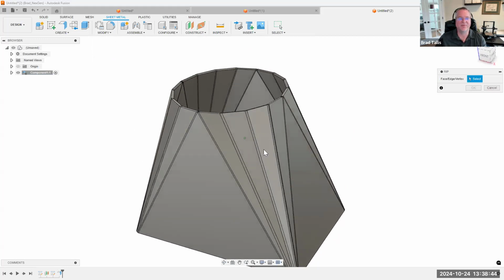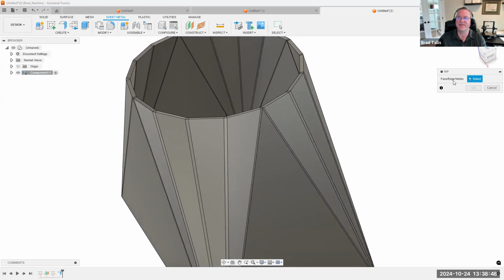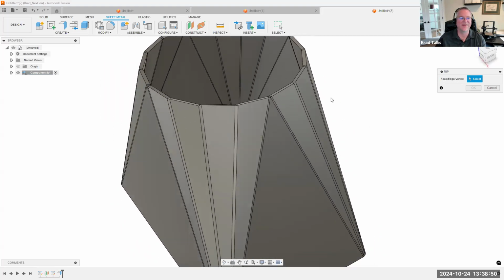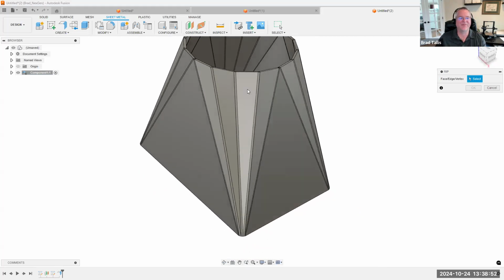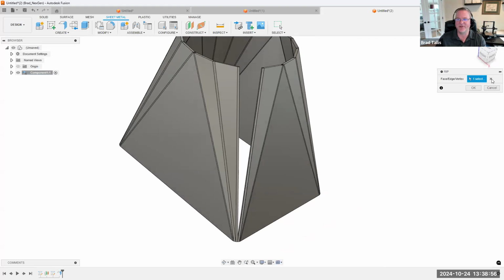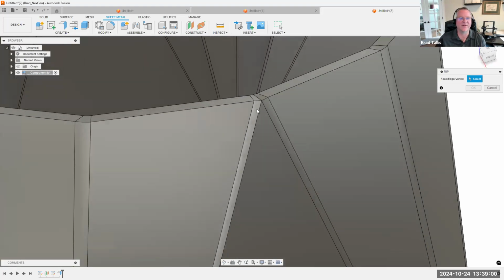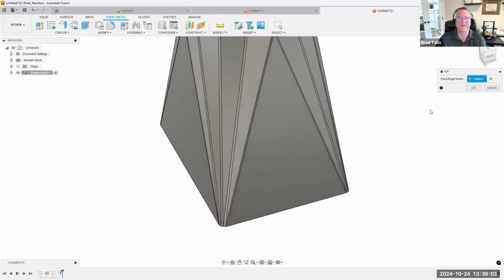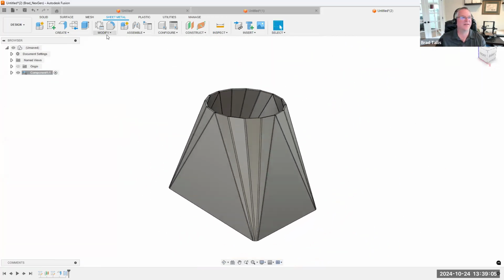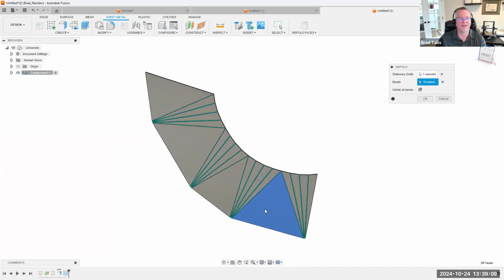And we basically need to rip open an edge. So I'm going to go ahead. You can see it says face, edge, or vertex. Now, if I were to click on face, it's basically going to remove that face out of there. So I wouldn't do that. But I might come in here and say like this face right here. So I'm just going to click on that face. I'll say, okay, let's do an unfold. And this time it unfolded.